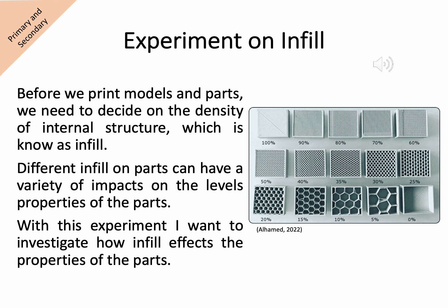Infill is quite an important thing we need to decide on before we print the part. This is done in the slicing software. The infill can vary from 0% to 100%, and the different percentage infill can affect the characteristics of the 3D print. This is something I want to explore with the CBA.